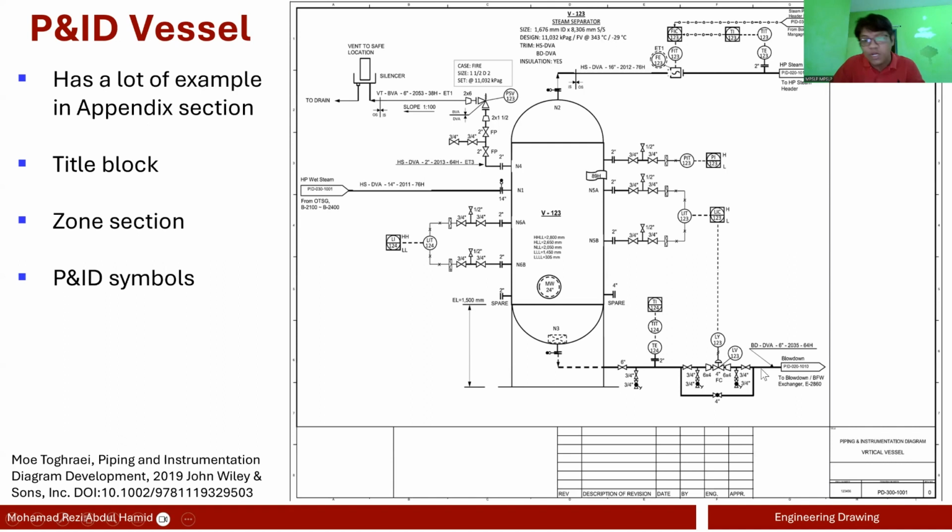Why is it set up like this? Imagine a situation where your control valve is broken, and you don't want to halt the operation. So how can I do a replacement without disrupting the entire operation? What I would do is very simple. I would close this valve. I would close this valve. And then I would open this valve so that the liquid can simply flow from here to the bypass line, and you can go here.